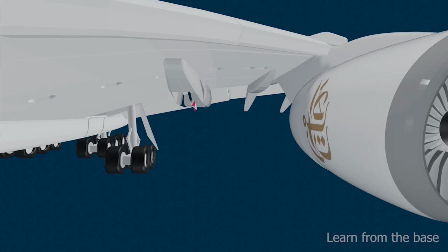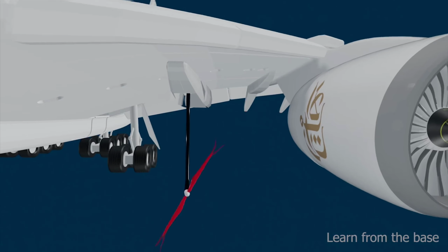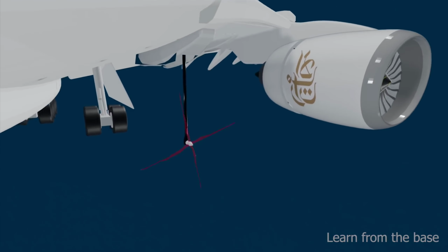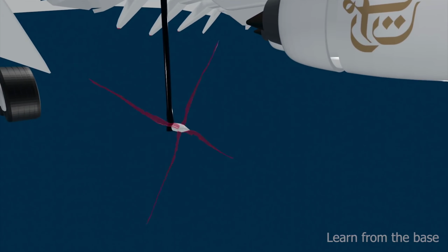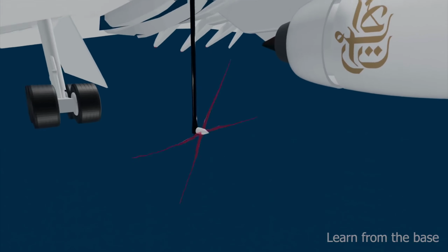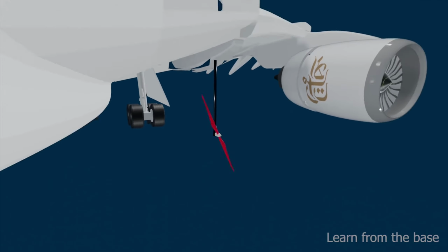This is the ram air turbine. It is a small wind turbine that is connected to a hydraulic pump or electrical generator. The ram air turbine is used only in an emergency. In case of the loss of both primary and auxiliary power sources, the ram air turbine will act as an electrical generator. It will power vital systems such as flight controls, linked hydraulics, and also flight critical instrumentation. Commercial aircraft can produce 5 to 70 kilowatts of electricity, depending on the generator.